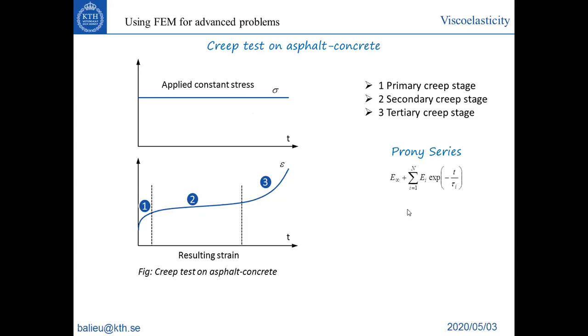What does this mean? By using a viscoelastic model, by using the Prony series, you will never be able to model the tertiary creep stage. This is due to the mathematical formulation of the model. You will never be able to do this.